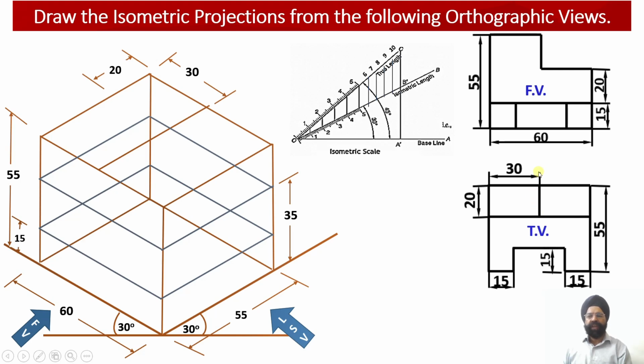So we are going to confirm this edge while we draw this projection line over here. Next, another projection line we are going to draw from this point up to this point, so that we can define or we can fix this width of the top surface of the web as 20 millimeter.